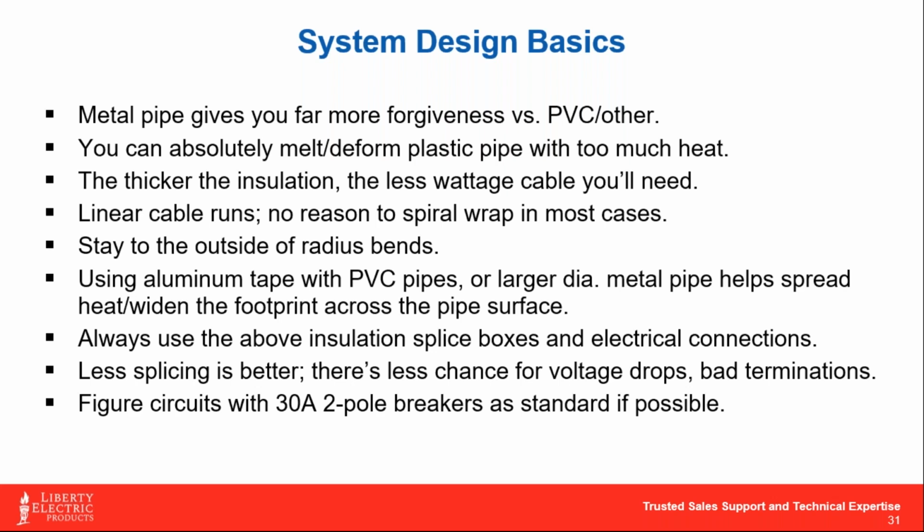So we talked about above insulation splices and electrical connections. Less splicing is better. Another tip that we would give you is always voltage check after your splice connection to ensure that you're getting proper current ampacity to the rest of that run. That's exactly why we try to reduce the amount of splice connections, because if the electrician digs a little bit too far into that bus wire and cuts out a few of those strands, you're not going to carry as much current through that as you would if you never spliced it at all.